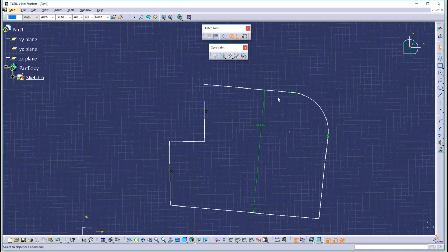So with these icons, a lot of times if you don't like what you see, you can right click and get some additional options. So for instance, let's say I have a circle drawn out here. Let's get rid of this tangency that popped up here. Okay, let's draw it again without a tangency. There we go. Now I want to make this circle tangent to this circle.